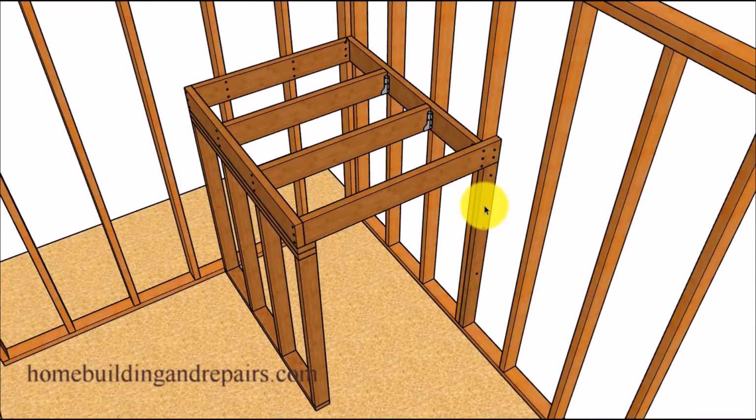And next up on the list, we have this construction method here that I believe is stronger, and it won't require a lot more materials, just one more 2x4 along with an extension of this joist. Now this idea here seems like it would provide a lot more structural strength because it's sitting on top of a wall here and sitting on top of a framing stud here, and will definitely be something to consider if you're going to have the upper stair stringers sitting on top of this part of the landing.